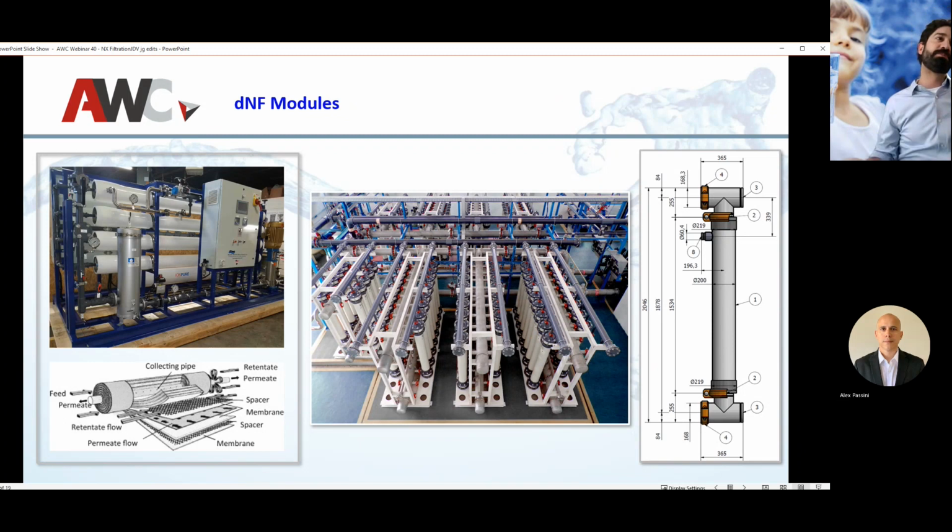When I talk about membranes, I should probably take a step back and say that the range of membranes that are out there are MF, UF, NF, and RO. That's from kind of more loose to more tight. MF is going to be like a 0.1 micron. UF will be 0.01 micron or so. Getting into Dalton range, it would be like 100,000 or 150,000 Dalton. Then getting into nano, it's tighter. For example, our nanofiltration membranes are 400 Dalton and 800 Dalton. There's another hollow fiber NF out there that's 1,000 Dalton. And then, of course, RO gets tighter, takes out more dissolved constituents.